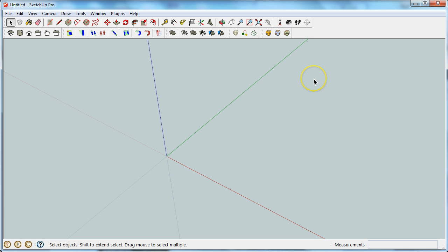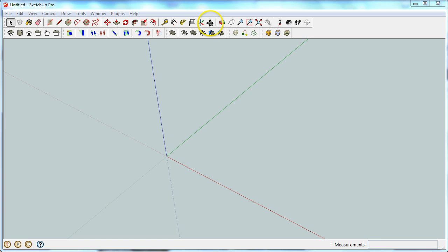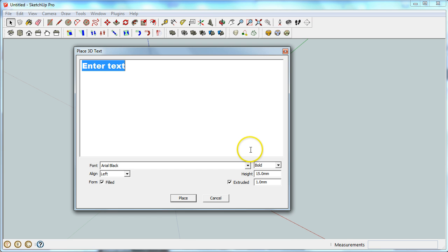So what we're going to do is use the Product Design and Woodworking Millimeters template like always. This one is going to be a little bit different because we're going to start with the 3D text tool, and the difference here is we're not going to use dimensions that make sense. We're going to use huge dimensions, and the reason for that is when you're using text, all these curved lines actually end up being in SketchUp a series of very small straight lines. And if you use text that was some size that you could accomplish on a normal 3D printer, those lines would be very small, fractions of millimeters, and SketchUp really hates trying to deal with those lines, and it gets very confused and very angry at you.